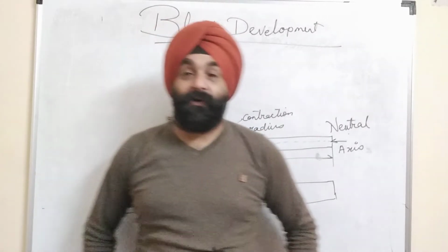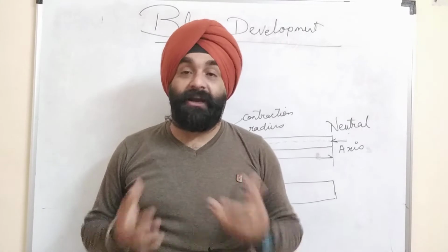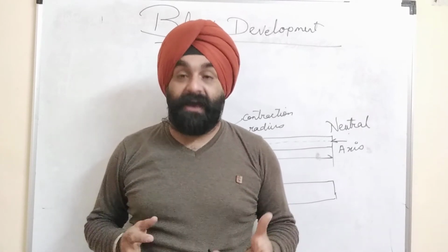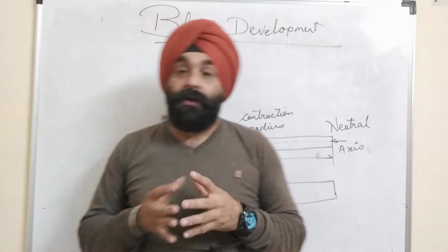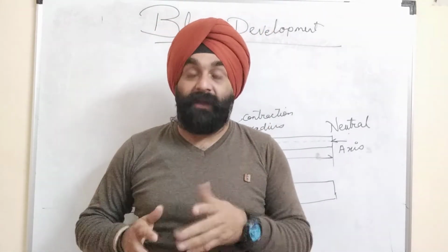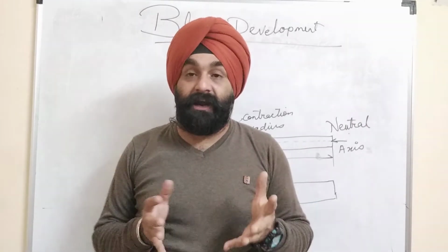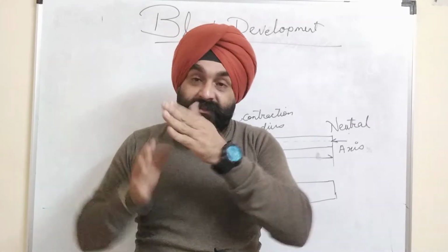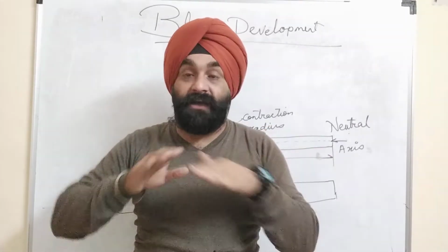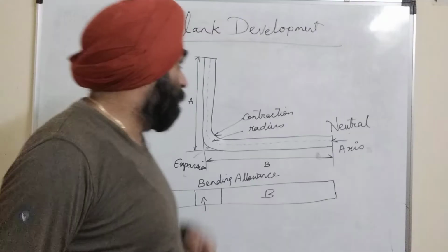Today in this video, I am going to cover a subject that is blank development in bending dies. So guys, whenever you receive any kind of bending tool, it may be the L bending or C bending or any other kind of wiping die, you have to first develop a blank, that is a plain sheet. So let's go ahead and study that in detail.